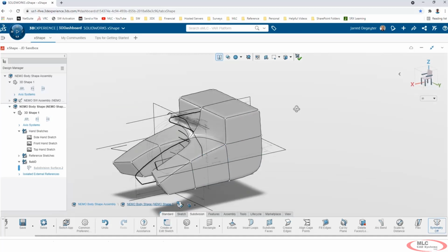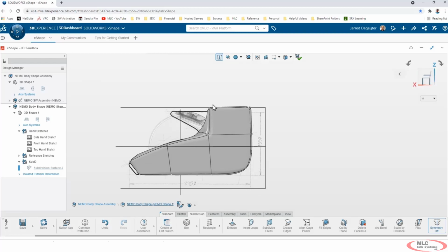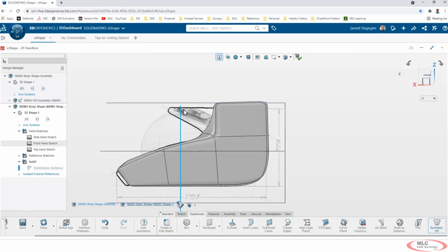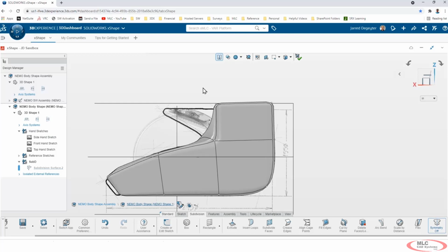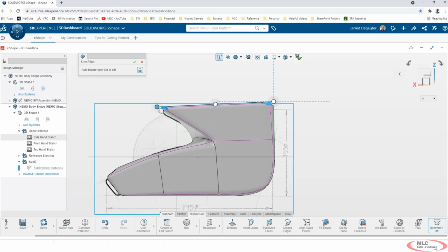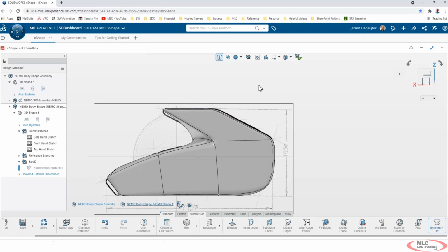Now what we've got to do next is get this top portion of our shape aligned with the sketch that's behind it. And this next tool I'll show you is really cool. It allows us to just basically box select those entities and then use this align entities by line, which gives us a line that we can drag around, and then those entities are just going to snap into position for us. So I can really quickly position things using this tool. So this looks a little bit nicer. This will snap and it'll be a nice horizontal style, or at least it would have been horizontal if I'd have released at the right spot. There we go. That looks a little bit nicer. I'll go ahead and we'll roll with that.